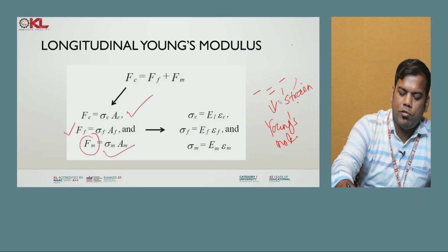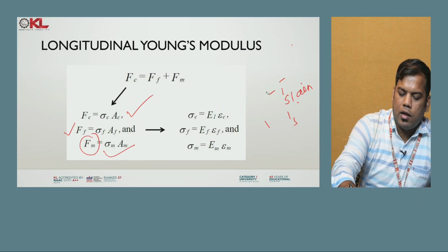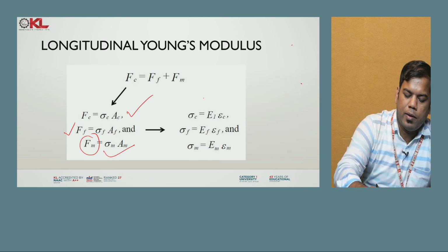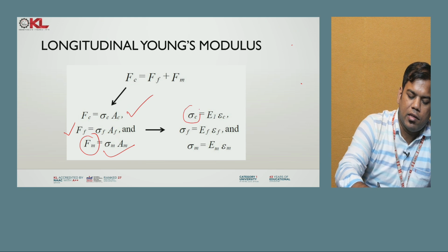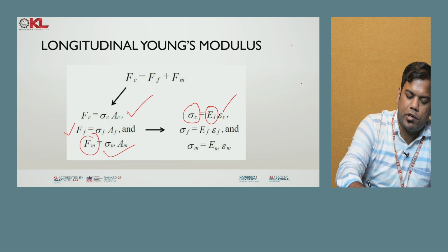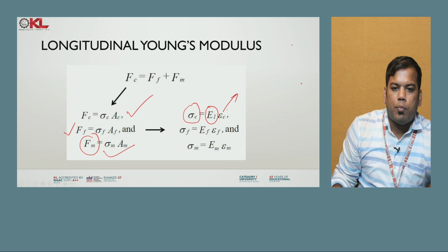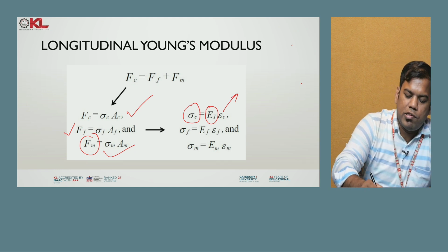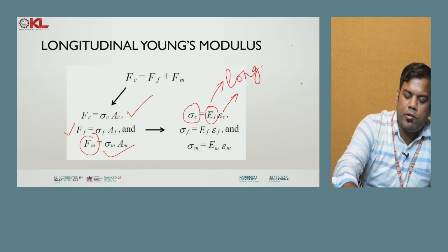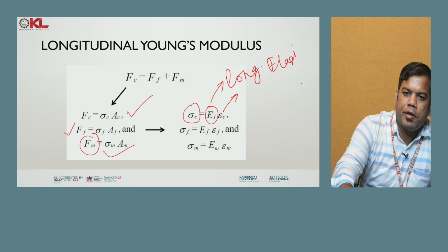Using this concept, the longitudinal stress for the composite, sigma c, will be equal to E1 into the strain of the composite, where this elastic modulus is our longitudinal elastic modulus.